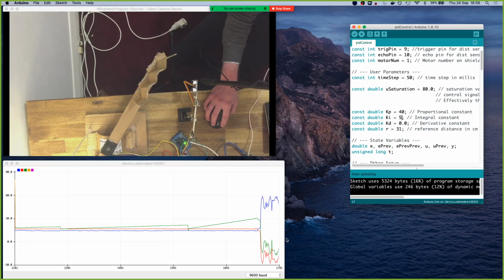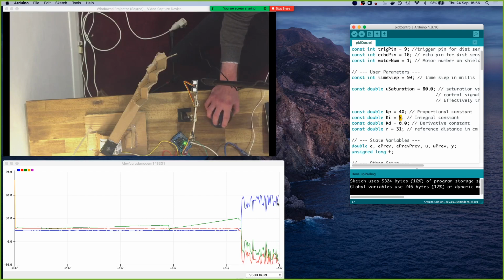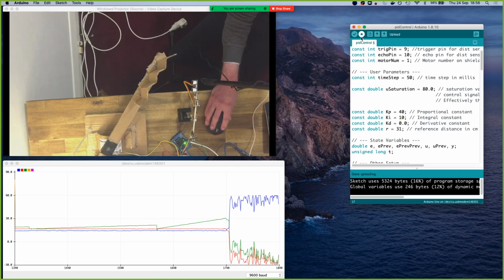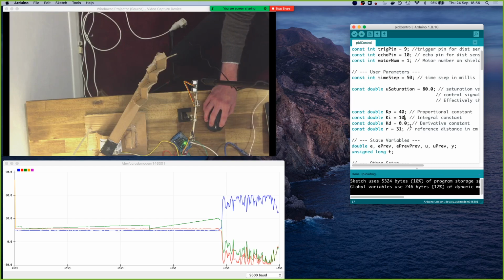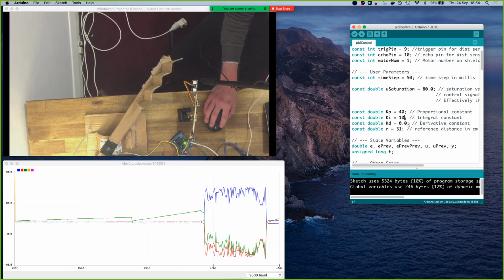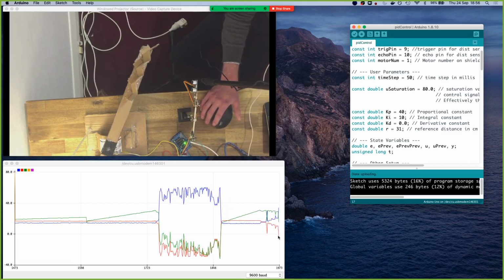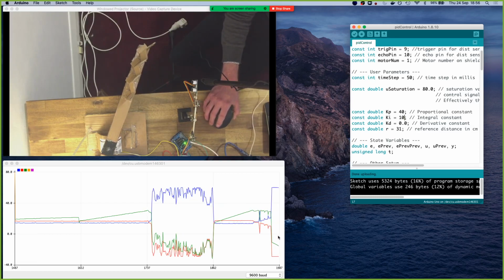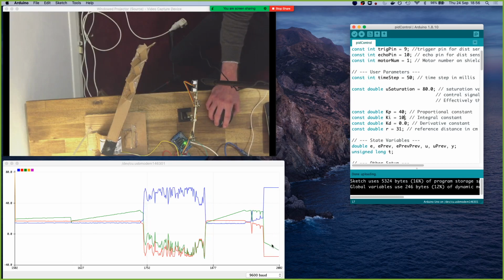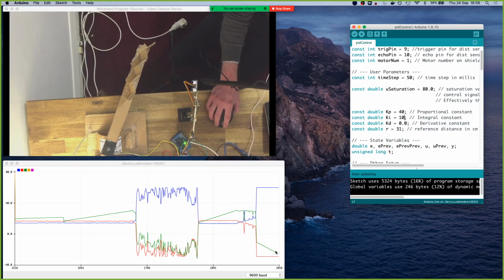Come on, motor, move. Could you feel if the motor has a little bit of a delay before it actually moves? Yeah, you can hear the motor whining, which has to do with the quantization. I think there's 8 bits of pulse width modulation, and as it steps through those lower level bits, you can hear the step changes. So maybe the inertia of the weight of the cardboard is something the motor doesn't account for. So it's doing something not quite what I was expecting. This has changed a little bit from what it was doing before. It's still trying its best though.